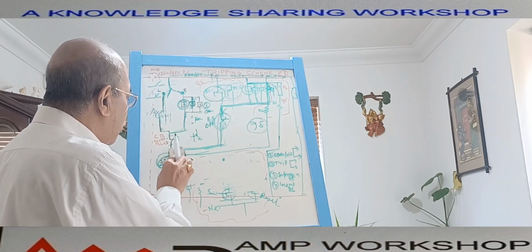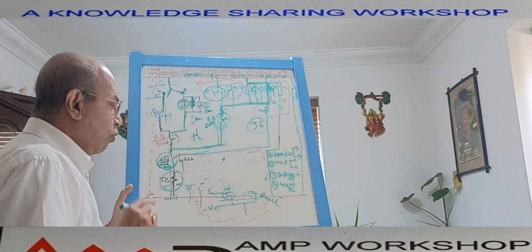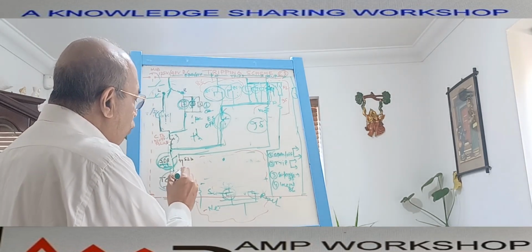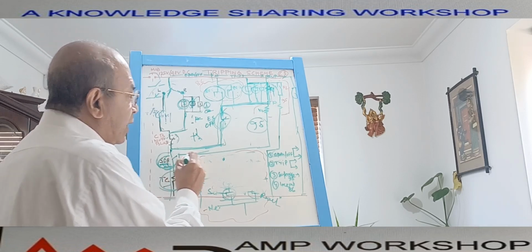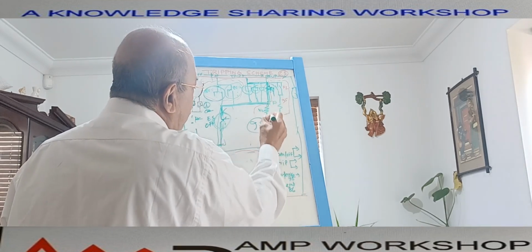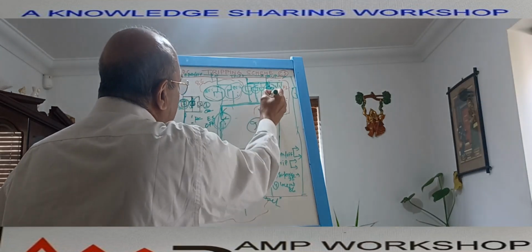So the power cannot flow through this because there is a NO contact, right? So it cannot flow through this. So what we will do at that time, we use the breaker NC contact. This is the NC contact, the 52B contact, that is getting energized through another coil. You see, this is a K2 coil, then K1, then the power will not flow through this way.